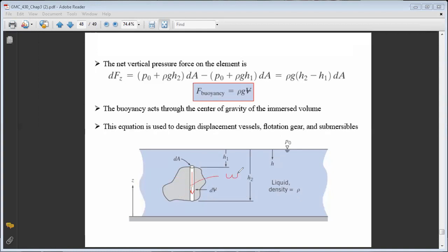It's also subjected to pressure forces at the upper level here. So it's P1, let's call it. If this is surface 1, this is surface 2. So the force here is P1 times dA. While if I take the bottom here, the force is upward because always the force of a fluid on an object is perpendicular, from the fluid towards the object. So this is P2 dA.